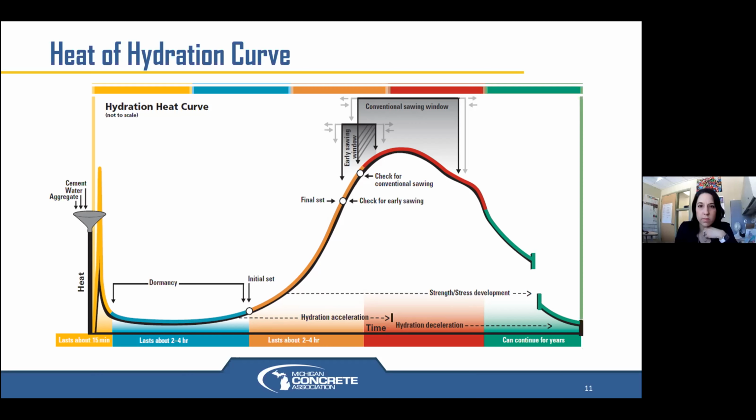Another one is on steel mesh. And that was one of your early slides, how we don't promote it because the cost of it and the very limited, if any, benefit doesn't make sense. What MDOT has found in the past is when they have older pavements that they used steel mesh in, if it gets too close to the surface they get delamination concerns, and if it's too close to the surface and they want to diamond grind that project to obtain some smoothness, that mesh can sometimes interfere with that diamond grinding if it is too high in the slab. So that's another great question there.